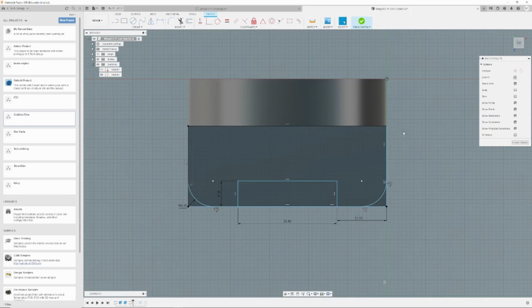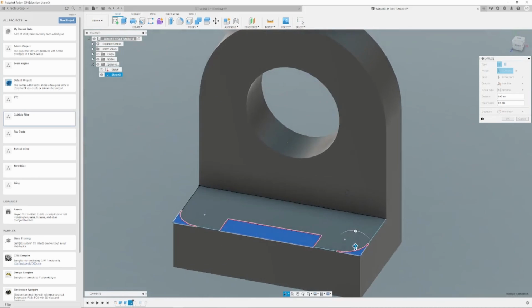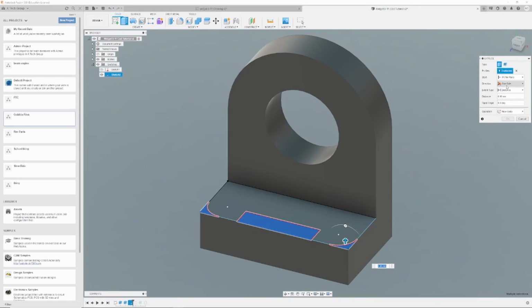Well, kind of. But now those are in the sketch so that we can grab these as part of the sketch. So we're going to finish the sketch, grab our Extrude tool, grab these 3 areas that we want to cut out, and we can pull it down so that it's cutting, and then come up here to our Extrude tool box, and there's a number of different settings you can use, but we're going to come to extent type: there's distance, to object, and all.